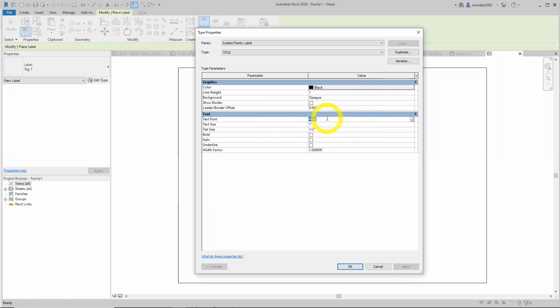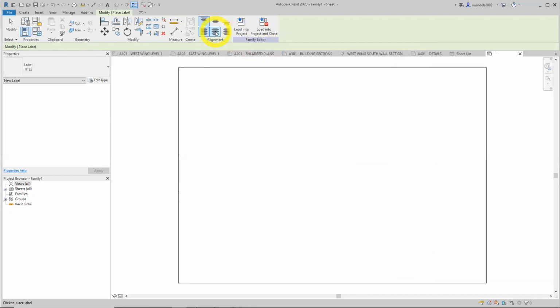It is Arial indeed, okay. We're going to click bold. Different options there. Width factor makes it fatter in width or narrower in short, basically. Okay. And alignment, let's do middle align and align center, vertically and horizontally. Let's just place it upper center somewhere right here.